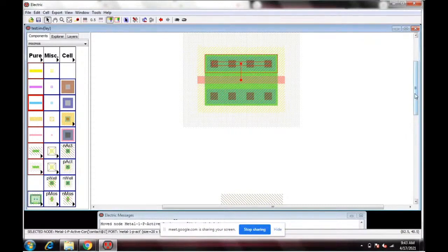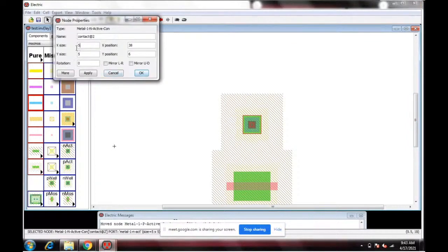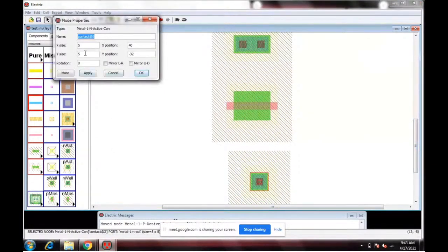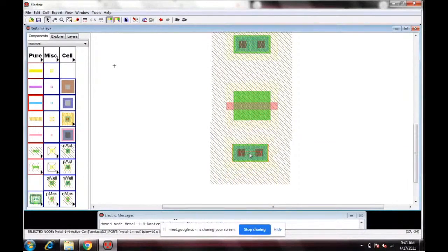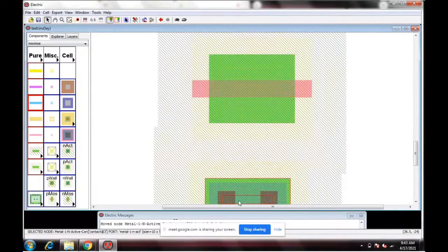Okay. So similarly for the NMOS, this width X unit, I will change it to 10, corresponding to the size of the NMOS transistor. Similarly, the other one, 10, for the NMOS transistor. I will align it and then I will move it. You can look here. You are getting the DRC rules displayed there itself.